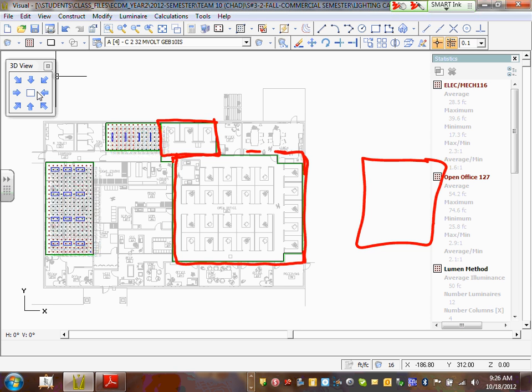If you drop this here, look what happened. If you drop it here, there is no way you can delete the background. Guess what? Because when you activate the background, it's going to look all over like this and it covers your stuff. You can't delete it if you drop it on the model. So put it to the side, activate the background, and delete it after you have moved the lighting fixture.